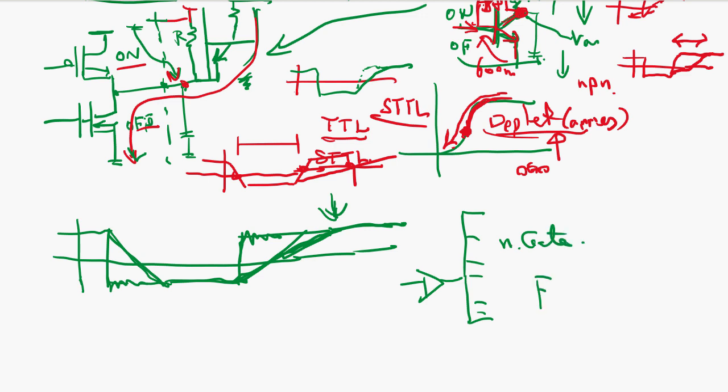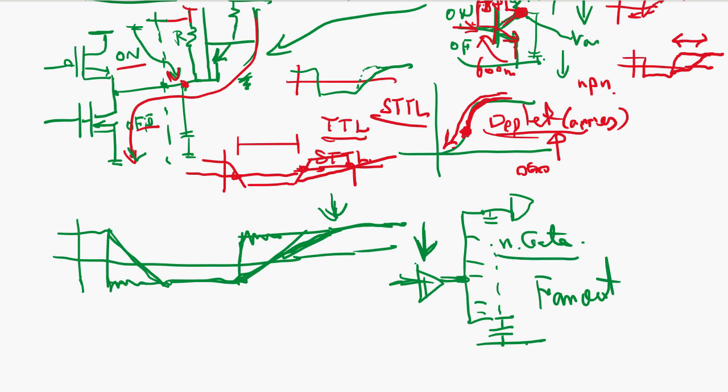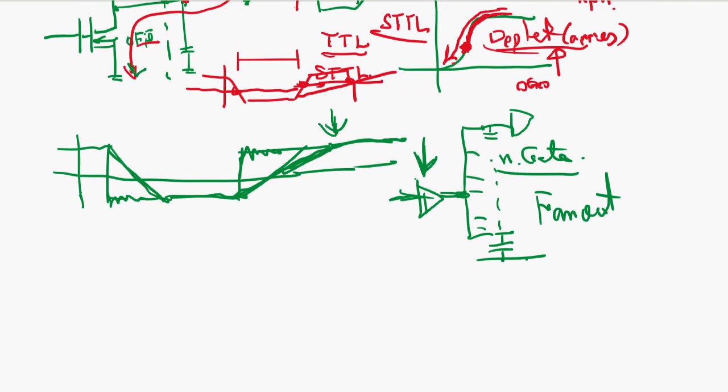It's called the fan out problem, because each gate input has a capacitor, and the total capacitance becomes so big, for this driver you have to use higher current drivers, high power drivers, to drive many gates. Okay, that's another issue in the logic design.